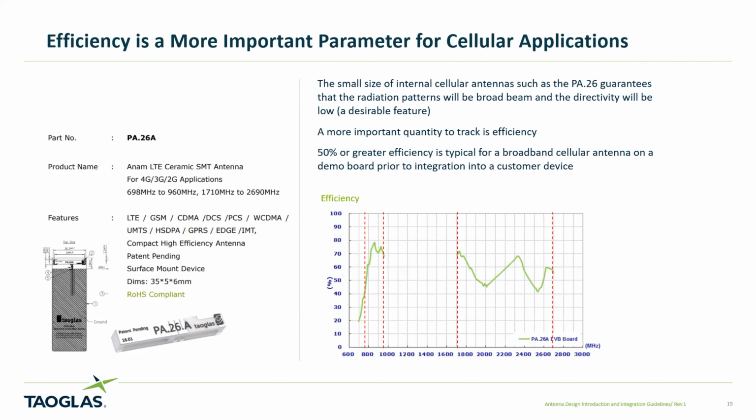if the design goal is to design an antenna in a client device that is going to be in a cellular network and it's going to be mobile, you don't know the orientation of the device and the orientation is changing. What you need to do is design, ideally, an omnidirectional antenna, one that radiates equally in all directions to handle that mobility part of the problem. As soon as you say you want 0 dBi directivity, or you want an omnidirectional antenna, that is 0 dBi directivity. Now, you need to apply a loss factor or multiply efficiency by directivity to come up with the actual gain of the antenna.